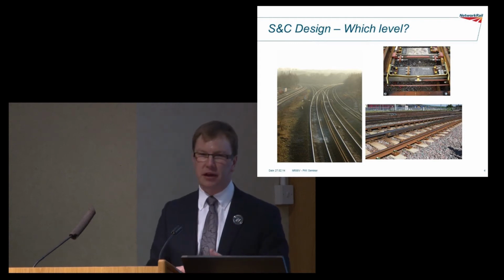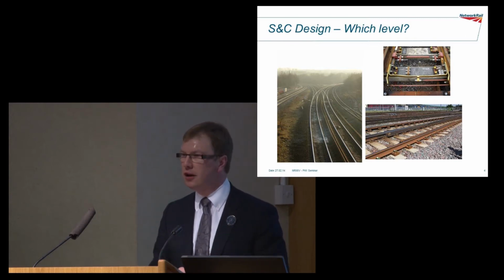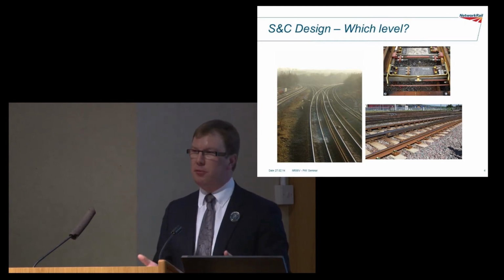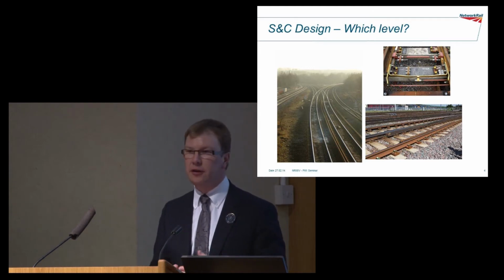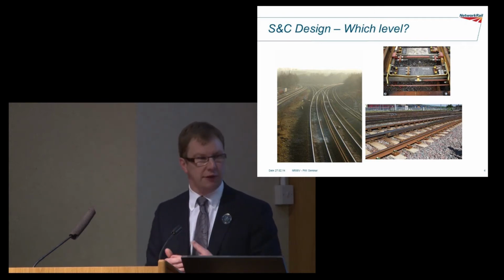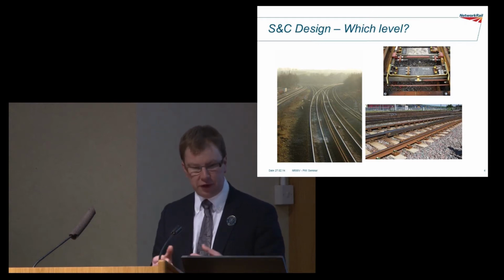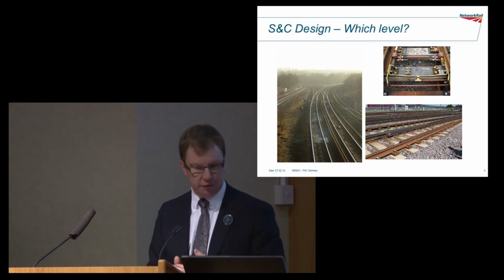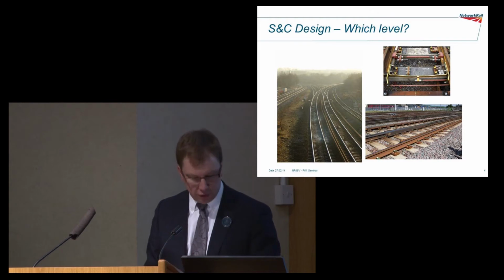People who are involved in scheme design are more familiar with the picture on the left there. It's how the overall scheme's going to go, what units of S&C we're going to put in there, how the geometry works. Then you get people who go into more the layout side and the sub-assemblies that make up the layouts, the switches and the crossings. And then other people are very specialised, they look at the component level. So the picture on the top right is very much saying the stretcher bars, the lock stretcher, the roller base plates and things like that. So they're all S&C design issues, all very different, and different skills are actually involved to do that design work.